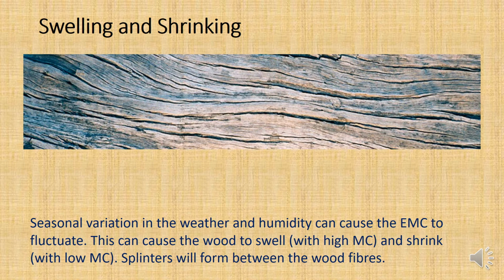Now, what happens with moisture content and its effect on durability? Well, remember what I said, that moisture inside timber sits between those fibers, those wood cells, and it actually expands the wood, because it means the wood cells are sitting a little bit further apart, because the water dilutes the resin, the lignin, that sticks the wood cells together.